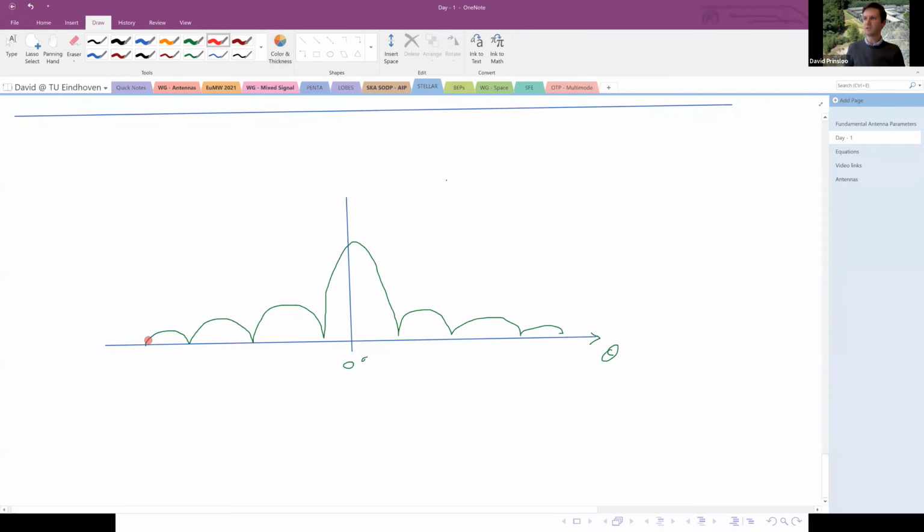If you were to plot that received power, you'll notice that they line up exactly on one another. So these two curves will actually just, more exactly than I can draw it, follow one another. And it's through this experiment that it is proven that antenna elements transmit and receive in exactly the same way. Of course, there's a lot of mathematical elaboration on all of this to prove it to you, but empirically, it can just be shown like this.